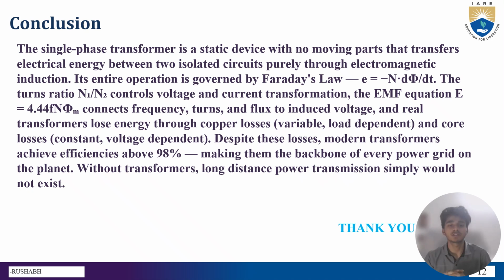Conclusion: a single-phase transformer is a static device with no moving parts that transfers electrical energy between two isolated circuits purely through electromagnetic induction. Its entire operation is governed by Faraday's law, E is equal to minus N into d phi by dt. The turns ratio N1 by N2 controls voltage and current transformation.